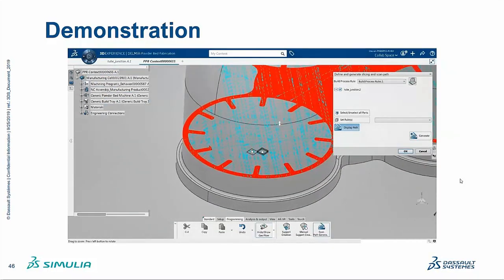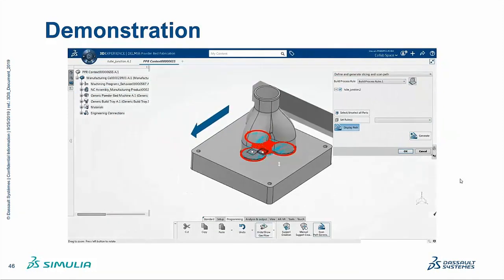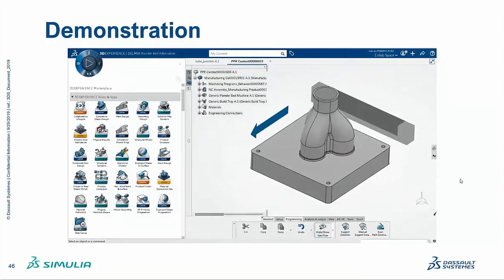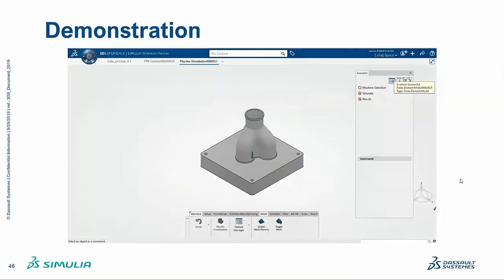We have a technique where we can assign eigenstrain according to the laser path. So you could have a different eigenstrain value, a different eigenstrain tensor, for example, in the surface versus the hatch pattern in the center. But here we just needed to define the simulation time.